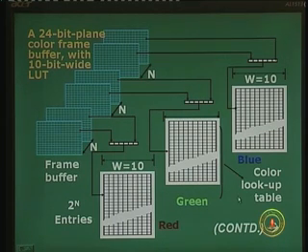That is an example of a color lookup table here. This is the lookup table for blue on the right hand side, in the middle we have the lookup table for green, and at the left hand side bottom we have the lookup table for red. It is not necessary that W should be equal to n. We talked about this earlier. In this case, we have assumed that the lookup table is 10 bit wide, W equal to 10 in all these cases: red, green, and blue.